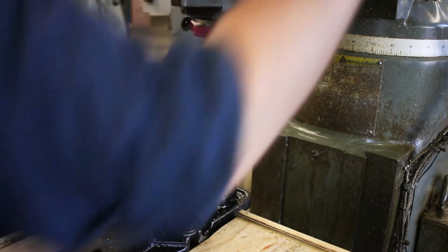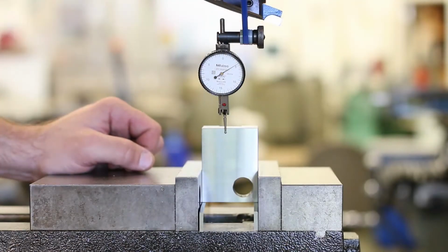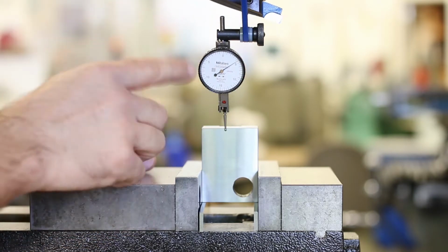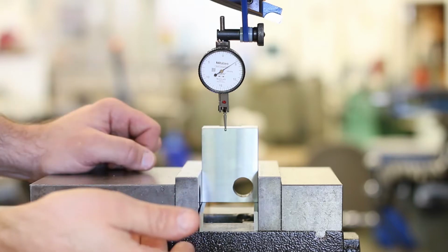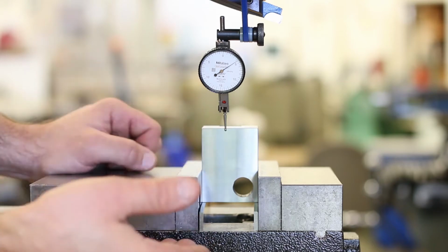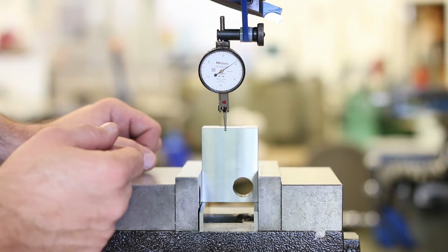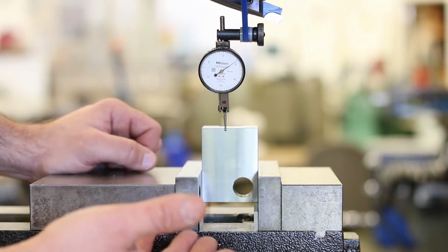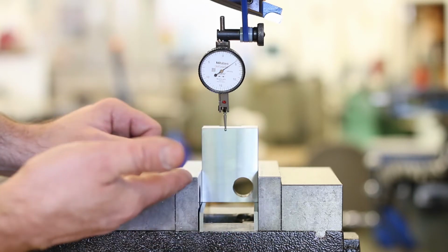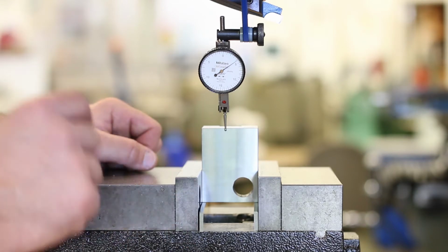Put it in low gear so it doesn't move around on me. Now I'm actually going to rough align the surface using the quill, okay? But I'm not going to trust the quill for final alignment. The knee is a much, much more accurate path of travel, which does not take into account any kind of tramming errors that we may have in this setup. But the knee is kind of cumbersome to move, and so just for convenience's sake, I'm going to rough align it with the quill and then go in just for the final adjustments and final inspection with the knee.